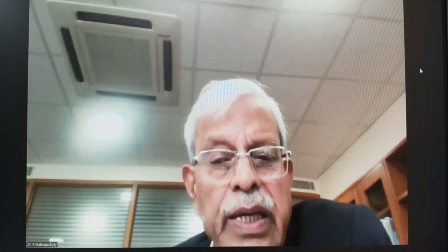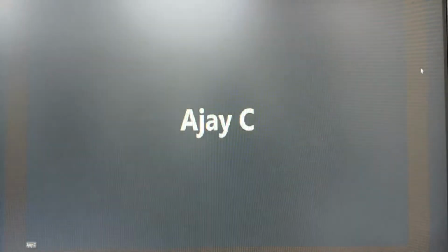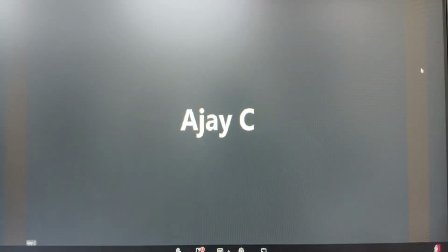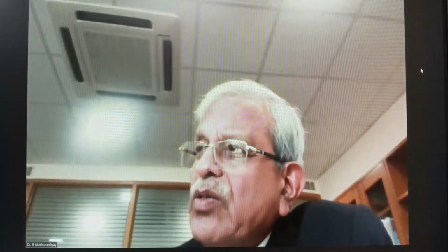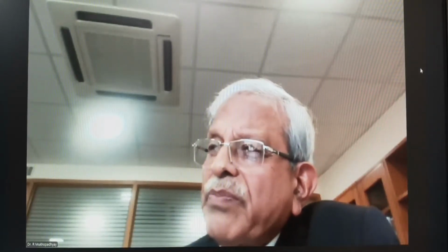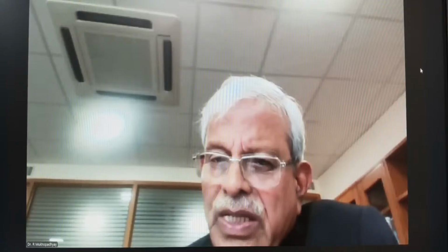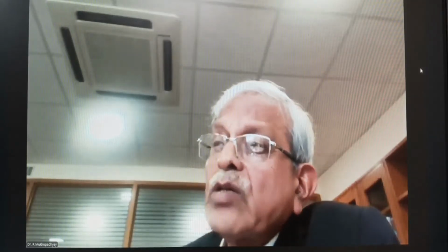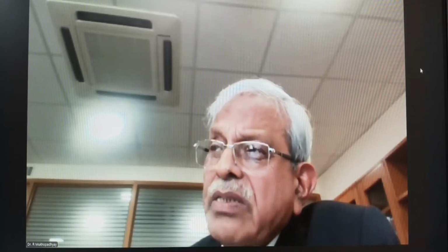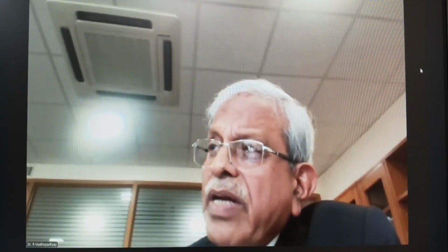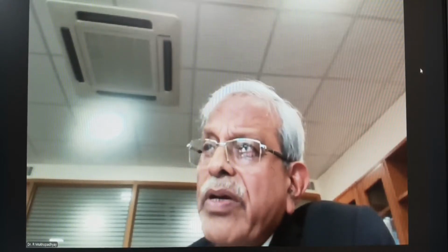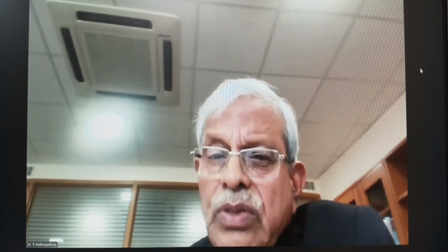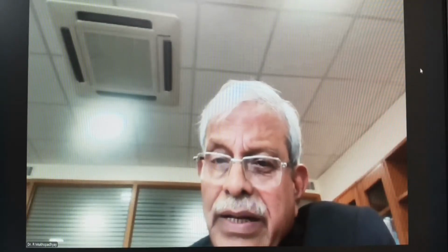Okay. Any other? The next question is whether a low glass transition temperature, Tg, compound is always going to give better abrasion properties. Let me be very clear, polymer is one part, about 45 to 55%, 50 plus or minus 5%. Other ingredients also play a role. Yes, you have to consider the overall Tg, not the polymer Tg. Suppose you take polybutadiene, Tg is about minus 90 degrees. But you cannot use 100% polybutadiene because of ride, handling and other characteristics.